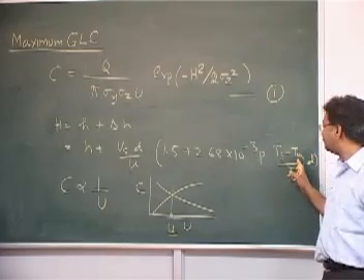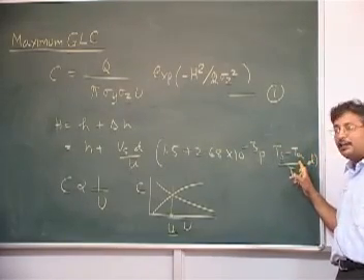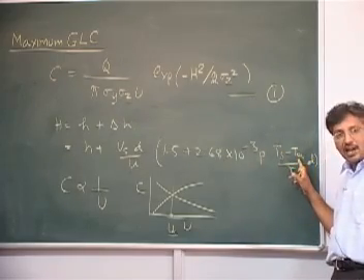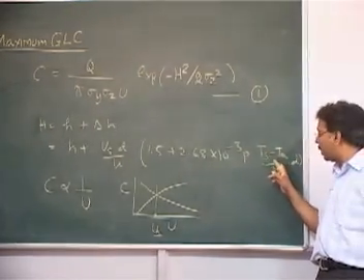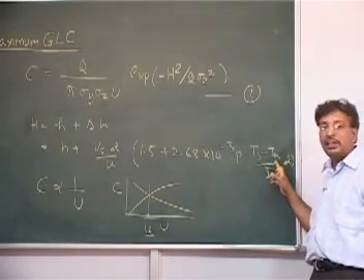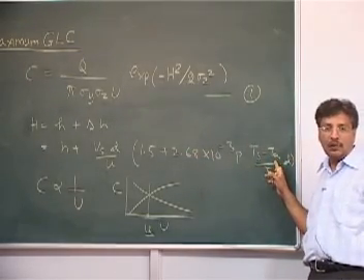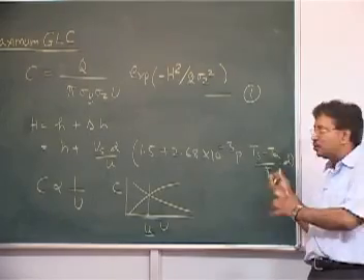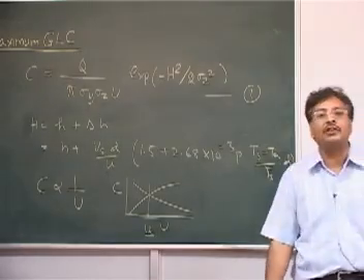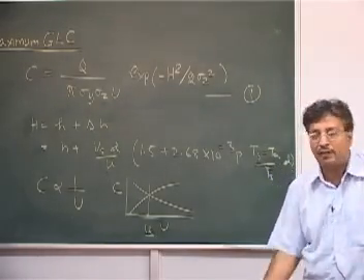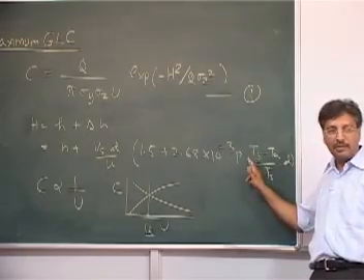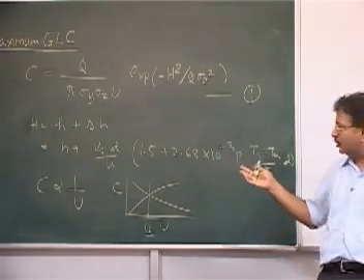And then you see here, when will delta H be small? When TA is large, because the higher the temperature difference, the higher the delta H. So criticality will occur when TA is high, right? In summer conditions you can assume this to be high. In Indian conditions, the ambient temperature you can take as 40 degrees Celsius. So I got this one fixed, this one also is fixed, nearly 1000 millibars or something.